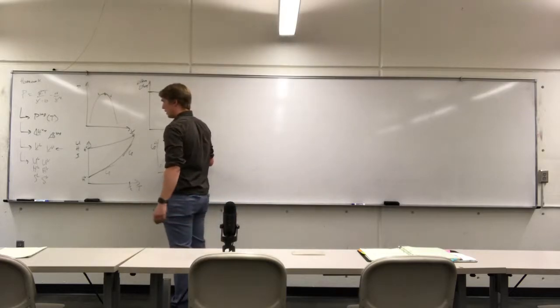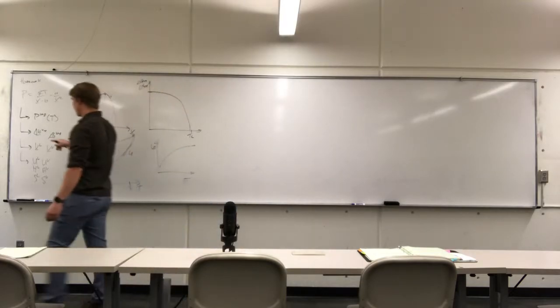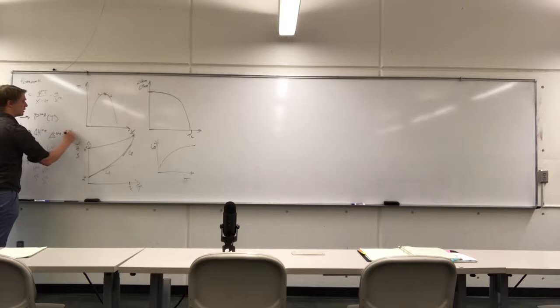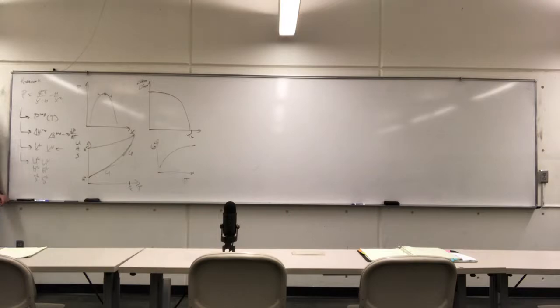So a couple of things. For the enthalpy and the entropy of vaporization, the Clapeyron equation is going to be your gateway into assessing it. So in this case, from here you'll get dP/dT, right? The change in pressure. Now this is the saturation pressure. So I'm not asking you to calculate the properties at all temperature and pressure conditions. I'm only asking you to calculate it at the saturation point. So for all of these, it's saturated liquid, saturated vapor properties for everything. Saturated liquid volume, saturated vapor volume. That's going to be your gateway into there.